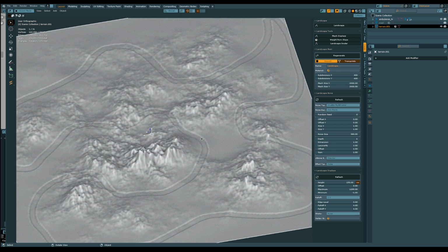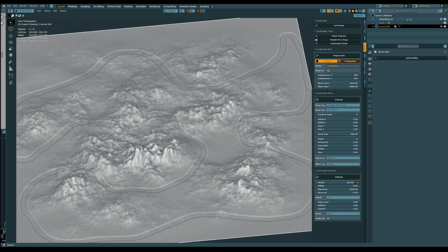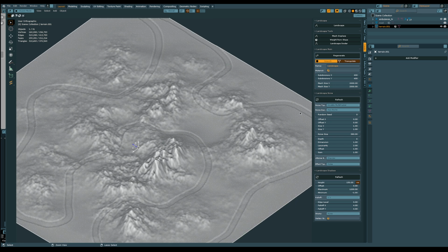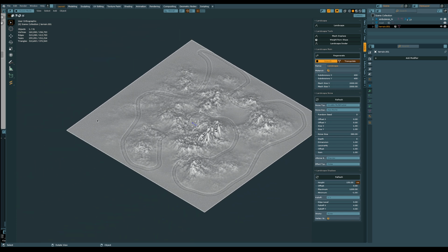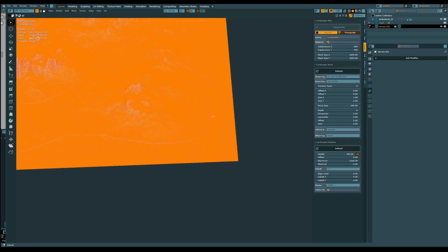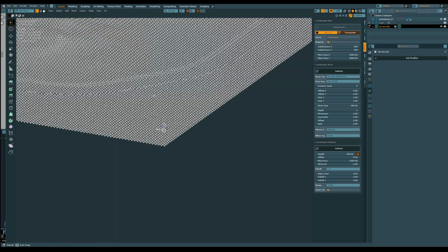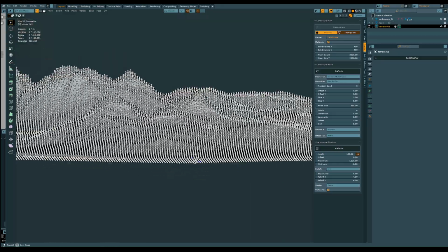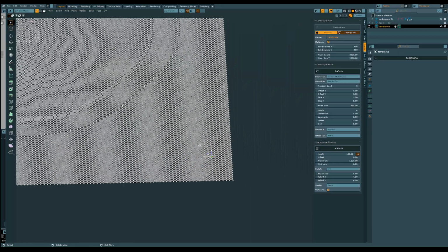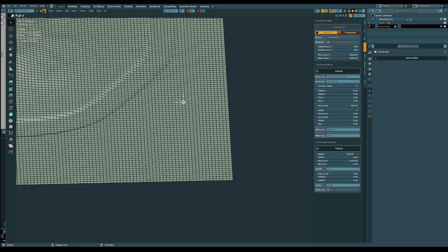You probably ask, but what's the right number? The right number depends on how big the terrain is, and we can play with these values a little bit. You see the flat areas in here, and there's a lot of stuff that does not need to be as dense as it is right now, because it has no bumps, has no curvature, has nothing. It's just completely flat. So we're going to be decimating this area that doesn't need to be as dense.